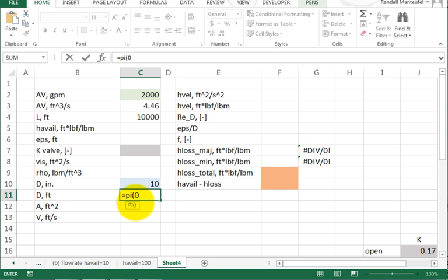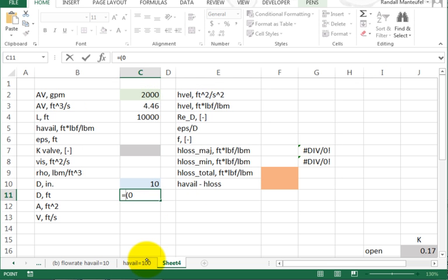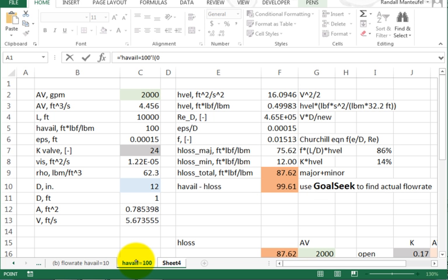In feet. What was our length? Pi. Oh, forget it. I already solved it. Let's quit. Okay, quit that. There. Did you guess I solved it before? So anyway, the GPM, and then this is the equation for that. I put the length there. Head available is what I'm going to check it against. There's that epsilon in feet. Is that the same value that we read off? 0.00015? Yeah. The loss coefficient for the valve three-quarter closed is 0.17.